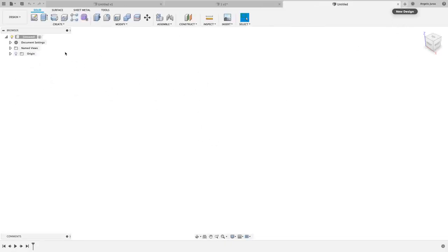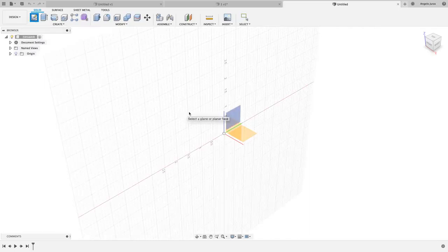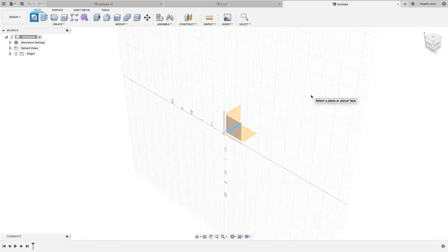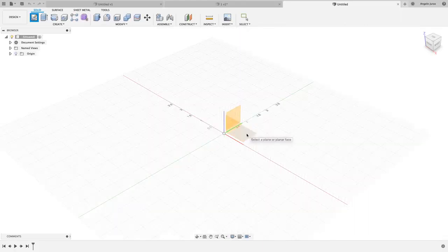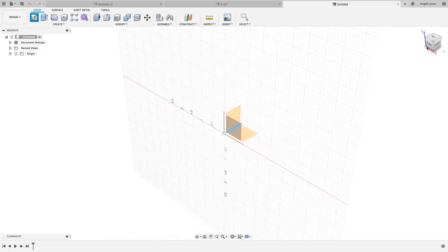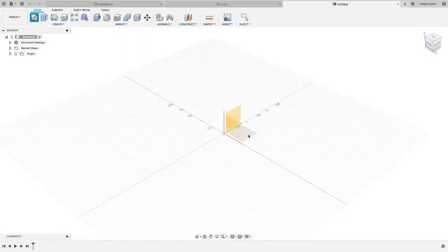Very first thing we need to do is create a sketch. And we're going to create a sketch on a plane. And if you've been using Fusion, you already know that you need to start here. And me as a machinist, I always like to draw on the X and Y plane, but it doesn't really matter because when you create your WCS, you define your orientation. Some people like to draw that it matches the view cube here. Doesn't matter, but for today's demo, I will do that.